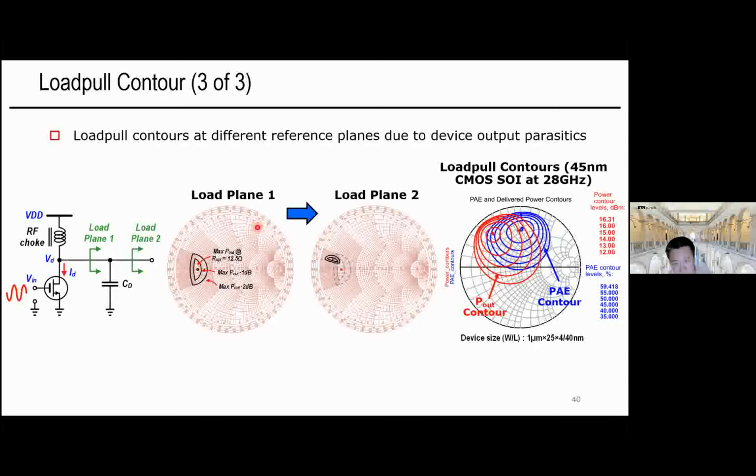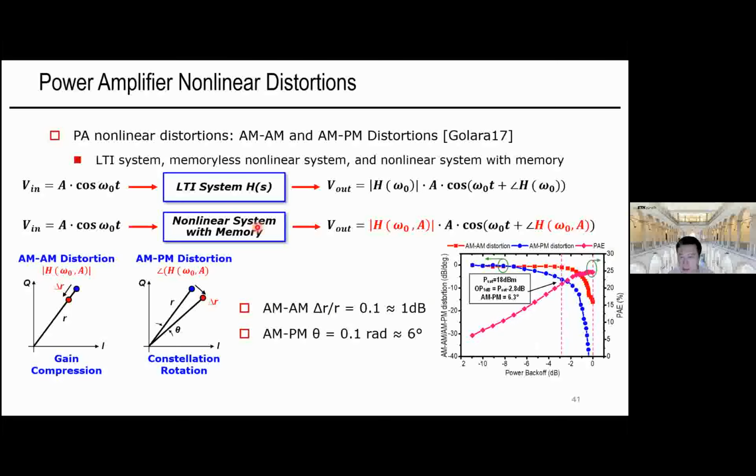It is very relevant, and I think you raise a very good point. I purposely don't want to go into the details here. For the stability calculation, we should talk about theory, and we should also talk about the practice, right? In theory, yes, you can use the stability factor K or mu. But in reality, these are all small signal estimation and small signal characterization of stability, right?